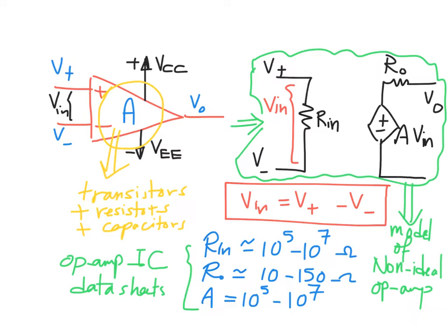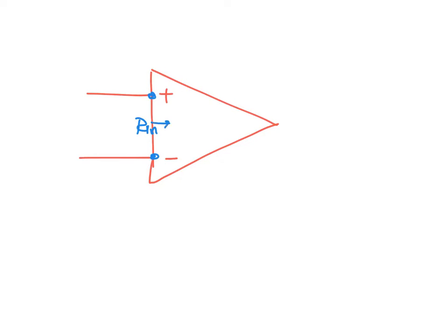So here, let's go again with what's called the ideal op amp. Here we have the operational amplifier model. We have the plus voltage and the minus voltage for the input terminals. We have Rn here going to infinity, which means we have an open circuit. And we have the output voltage here, Ro goes to 0, which means there is a short circuit here.